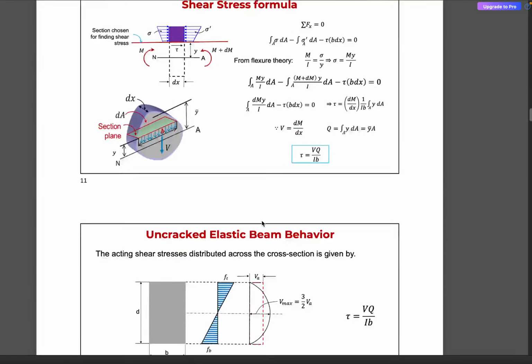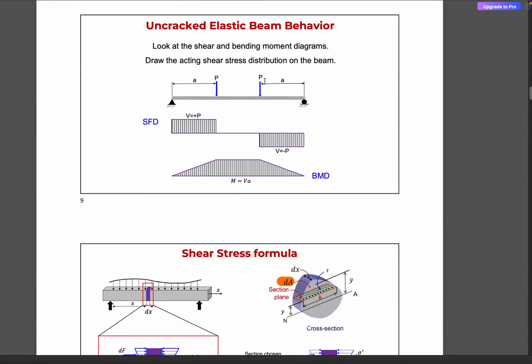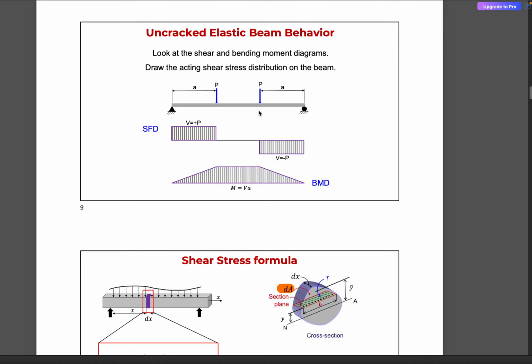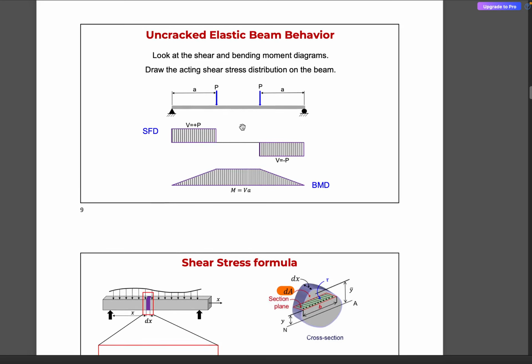The concept of shear span was introduced in order to discuss the significance of the location of the point load on the development of flexural or shear stresses. It is particularly considered a point load because we wanted a particular length of the beam which was under a constant bending moment. That is only to give an idea as to how the stresses develop in a beam, whether flexural or shear stresses, depending on the location of P. I think that was the only point, and I don't think it is really important if you consider a UDL.